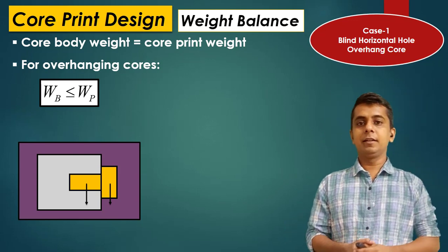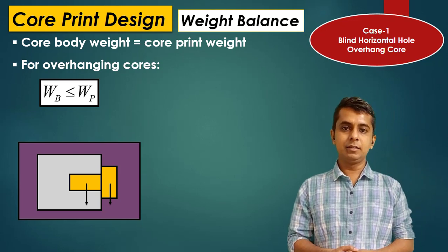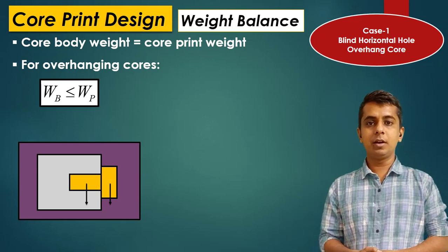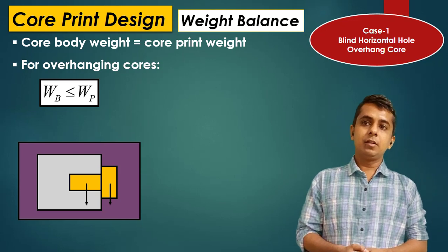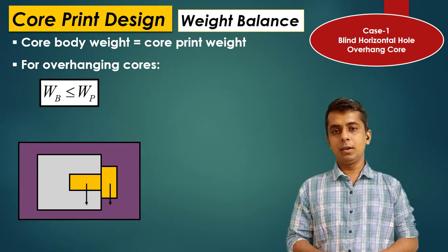So to prevent that buckling, the weight of the core and core print should be balanced.